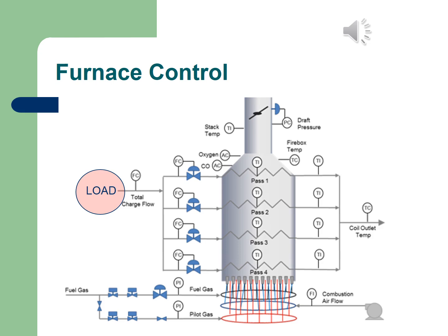And then this is basically the pressure that's measured on each line, and also, of course, what's important there on the exit of that load through the furnace, you can see that there are temperature measurements, because that's eventually what we want to achieve. We want to raise the temperature of the load by using the furnace equipment, and then eventually have the proper heat transfer from the heating air that flows through these tubes, and then we need to measure the temperature at the coil outlet. You can see that TC there.